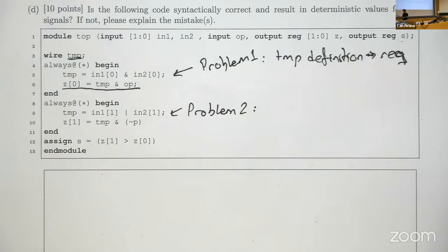So you have two combinational circuits driving the same signal. But those circuits can be different. And how do you connect two output wires of two circuits to a single wire without using any gates and stuff? And this is the problem here, basically. So I think this is called the multiple drivers issue.